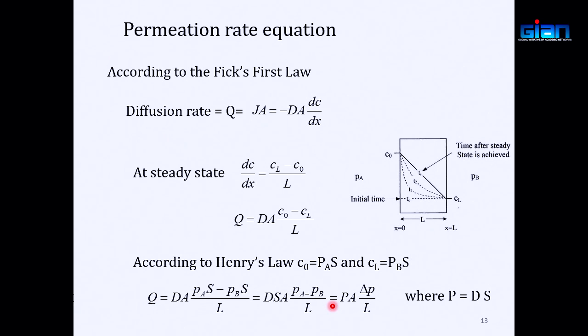Or you want a certain time in terms of the shelf life, 1 year, 2 years. Then you put that time in this equation and then you say, oh, what would be the permeability I need for that film that will give me that much shelf life.